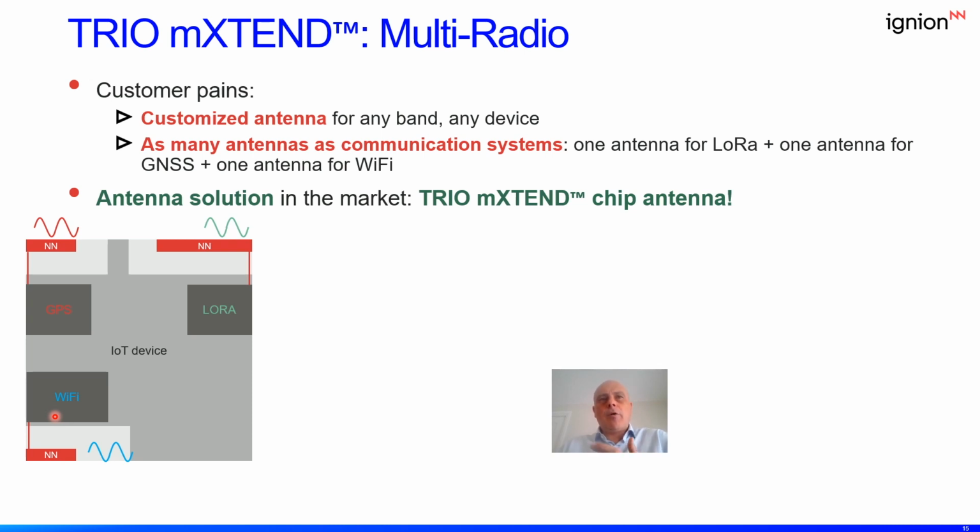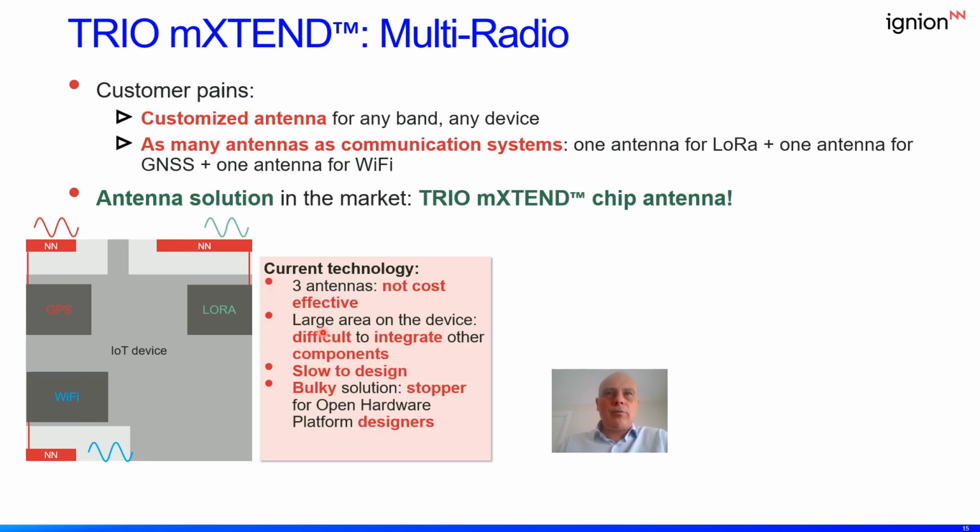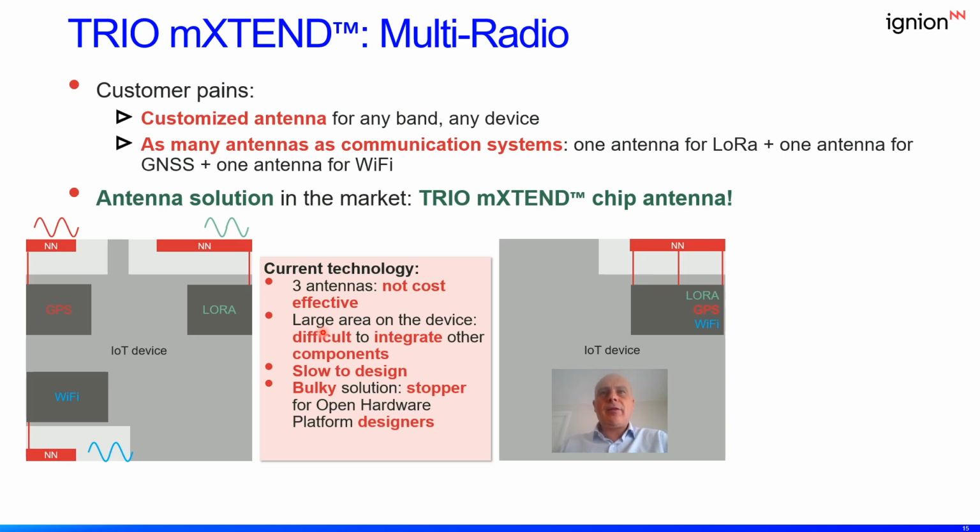The common sense approach will be to use 3 different antenna boosters for each radio. Each antenna booster will be connected to a different transceiver. This occupies space on the device, and this is not an optimum solution. However, thanks to this flexibility in virtual antenna, we can have 3 ports on the same antenna chip.